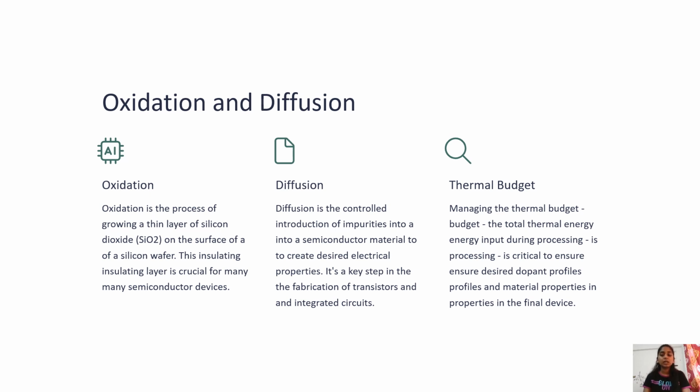Thermal budget. Managing the thermal budget, the total thermal energy input during the processing, is critical to ensure desired dopant profiles and material properties in the final device.